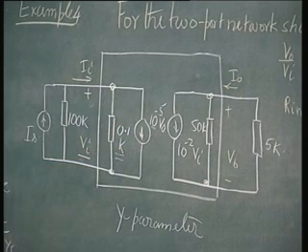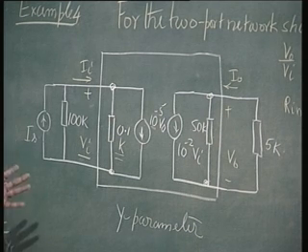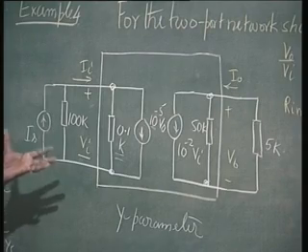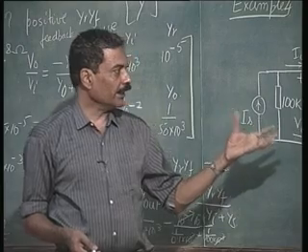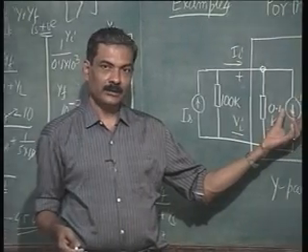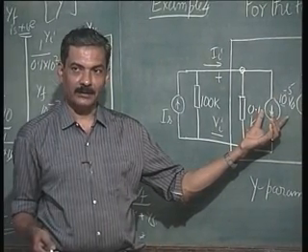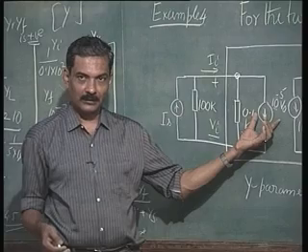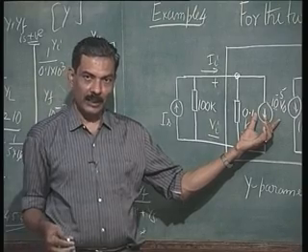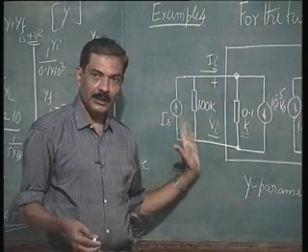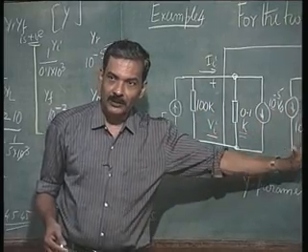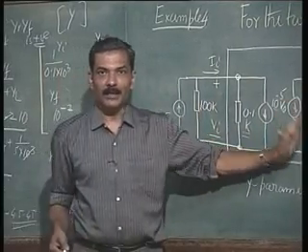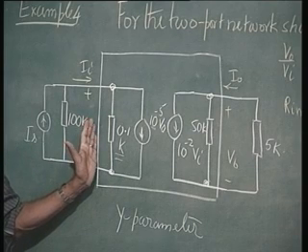Henceforth we will assume that for all our amplifier discussion, until we again raise it, the reverse transmission is 0. I just wanted to bring this about so as to make it clear to you that this factor is sometimes a troublesome factor in amplifier design. Okay. An amplifier has to be unilateral. It has to transmit only from input to output. There should not be any feedback. It is this feedback which causes most of the troubles faced by designers of amplifiers.